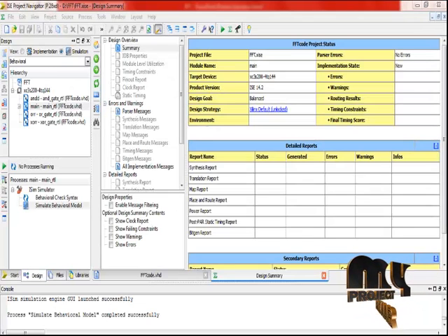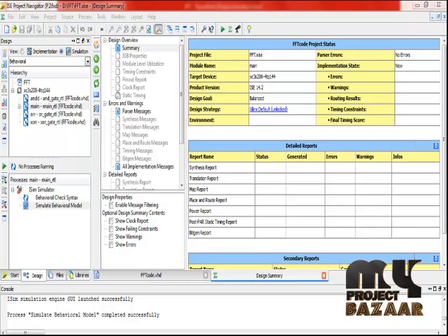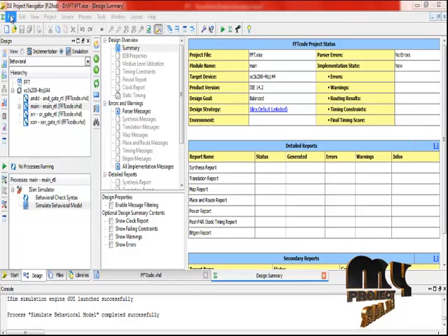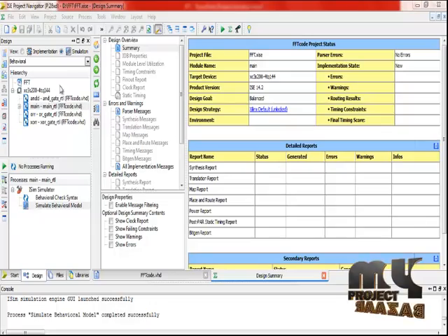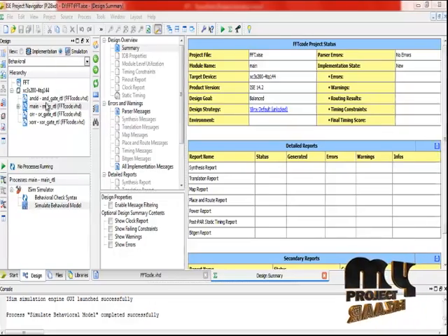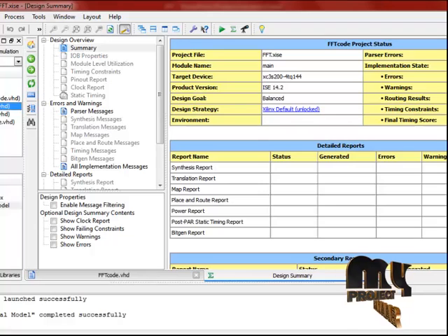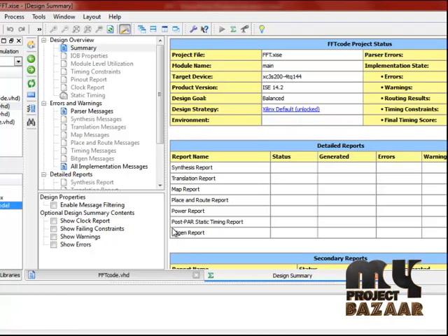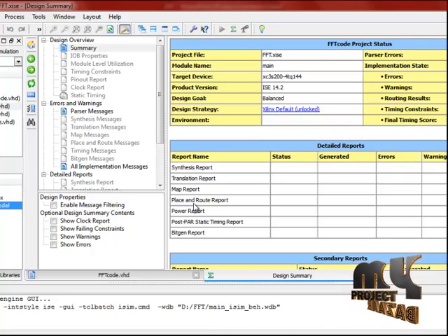Finally, we are going to see the output for our project. To create the new file, we have to go to the file function and create the new file function. We have to specify the folder to which we have to save the file. The new source is created for the programming space. Then to simulate our program, click on simulation and main and double click on simulate behavioral model. The simulation process will be running.